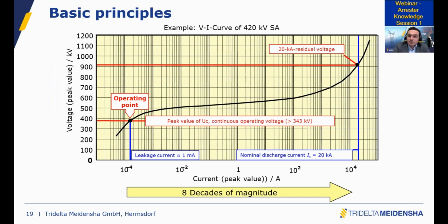The main challenge when you design a surge arrestor, but also when you manufacture metal oxide varistors, is the ratio between your protection level and the operative value. Typically, the rated voltage of a surge arrestor is a TOV value, temporary overvoltage, for 10 seconds with prior duty, which means that your surge arrestor has been pre-stressed to be in the worst case condition.